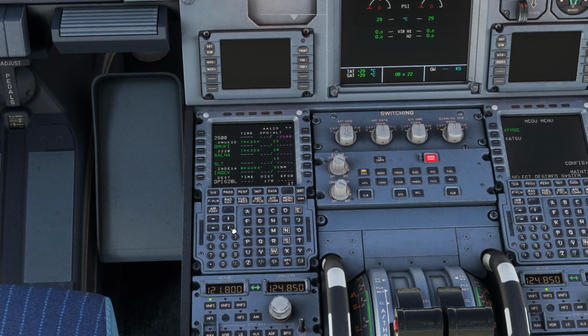Now you have to check the secondary flight plan. You can copy the active secondary flight plan. It is actually for different procedures. So let's say in case of an engine failure, you should have your secondary flight plan, so you can change it and then you can just fly back to the runway.